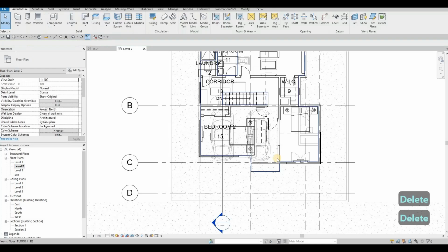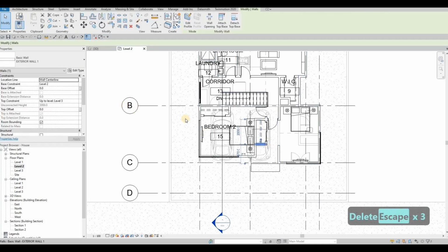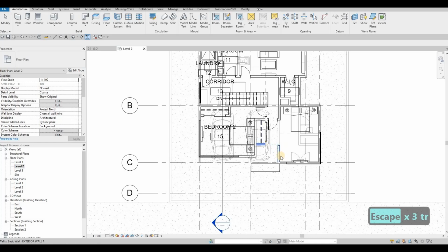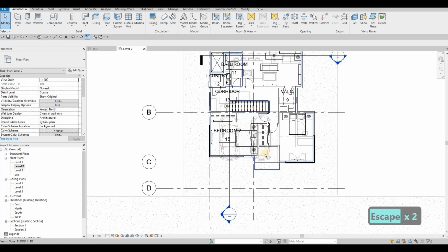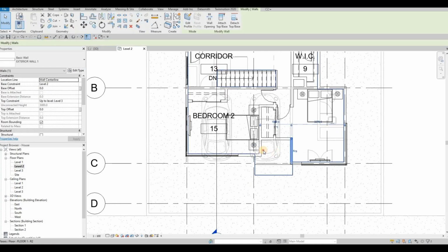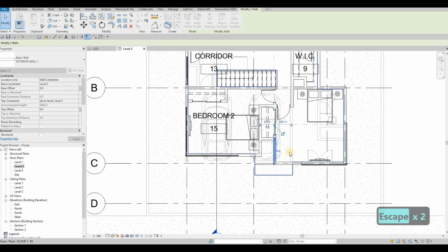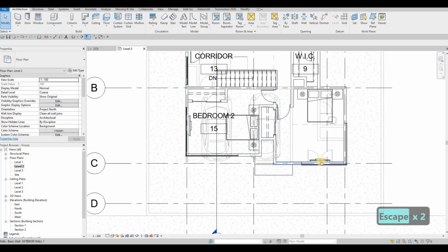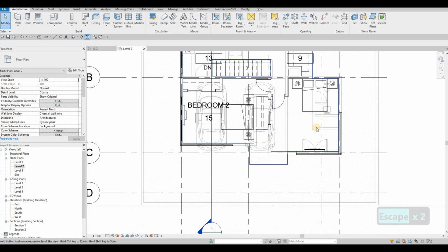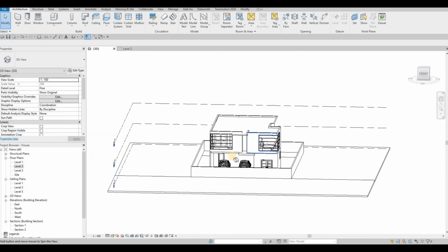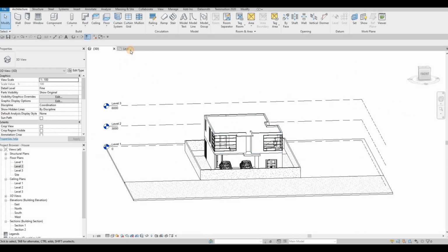And then we could just delete this part right here. Delete this. And then convert this, already converted. TR, trim and extend all the way right here. So we're gonna remove that notch right there. We can even extend this one now actually, because this is only a small part right there. So I'm just extending this, so we have a lot of areas right now here. So we only have this notch there.